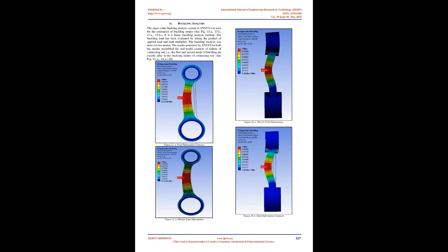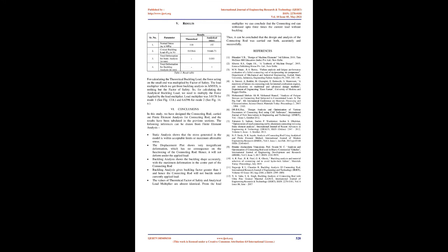Conclusions. In this study, we have designed the connecting rod and carried out finite element analysis for the connecting rod, and the results have been tabulated in the previous sections. The following inferences can be drawn from finite element analysis. Static analysis shows that the stress generated in the model is within acceptable limits or maximum allowable stress. The displacement plot shows very insignificant deformation, which has no consequence on the functioning of the connecting rod. Hence, it will not deform under the applied load.